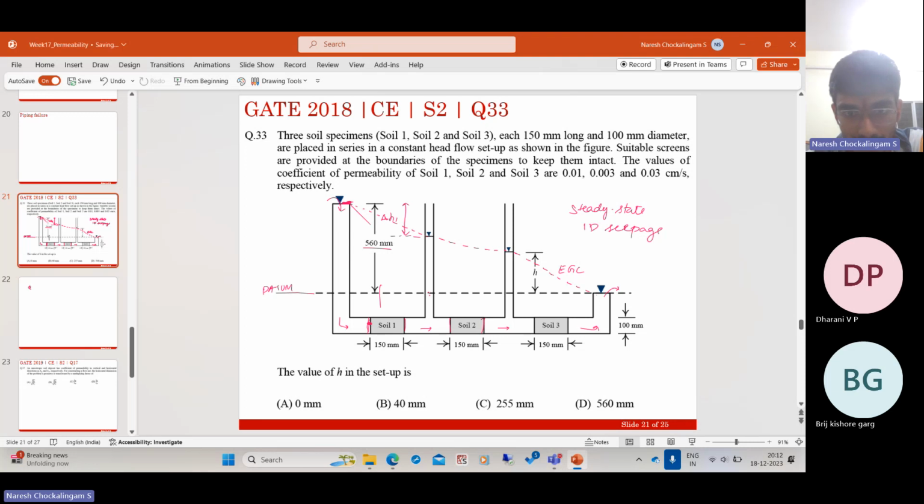Similarly, take this point, right? If you take this point, elevation head is the same for all the three, and the pressure head at this point is so much. So the total head is here. Similarly, at this point, the total head is here. Therefore, this line which I have drawn in pink measures the variation of the total head along the direction of flow.